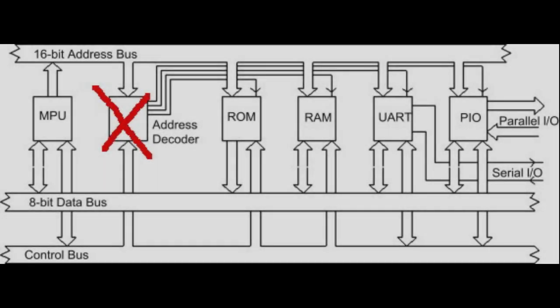So let's suppose that we are debugging a non-working microprocessor unit, which could be a computer, a 1541, an arcade game, or anything else with a similar architecture. And let's suppose the address decoder has some faults. The address decoder in the actual circuit may be a number of different TTL chips connected together, for example.